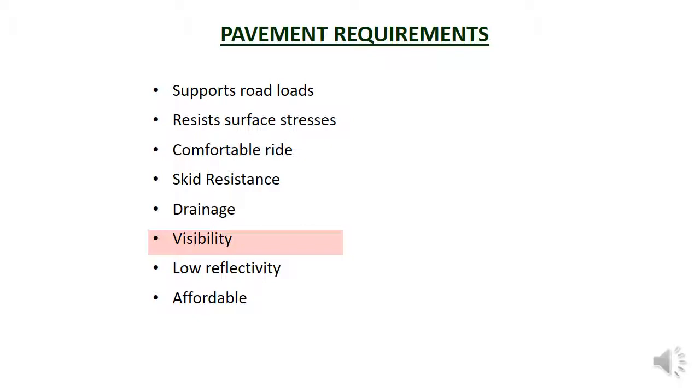The extent of the road and road markings need to be seen clearly in all weathers. Head-on crashes can occur when drivers cannot see the road centreline, or cars can lose control in unsealed road verges if they cannot see where the road edge is. The road surface also needs to have low reflectivity, which means that sunlight and streetlight reflection off the road surface does not dazzle or blind the driver. This is especially a problem when the road is wet.